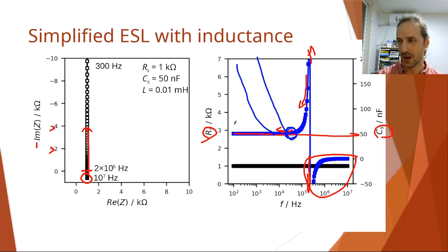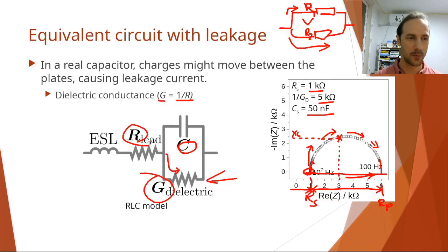So this is why I personally always prefer to plot the impedance, draw up this equivalent circuit, and let the software, specifically the impedance measurement software, which usually lets you make this model circuit, fit the curve and then calculate everything you need.